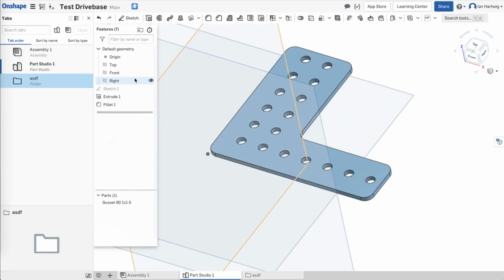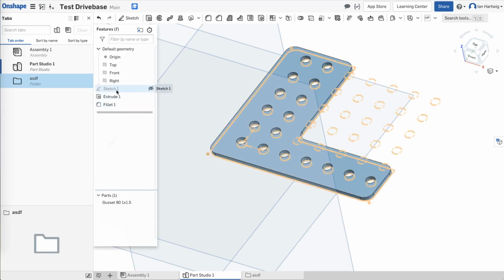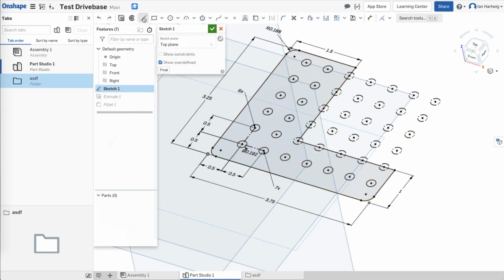So let's go back and actually add a whole new feature. This is good in a lot of cases, but there are some places. We had some gussets that another team used at Chesney that actually had a piece of metal going across this rib, and that can make it so that there's not as much bending load on this corner. So let's go back and actually add some kind of complex geometry to the sketch. I'm going to start with a line over here. So we're going to fill in this corner, but we actually want to define a rib over here.